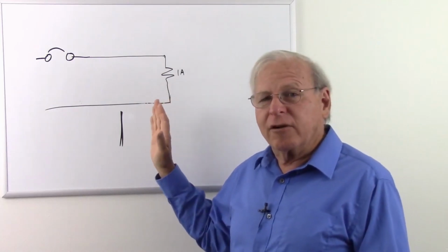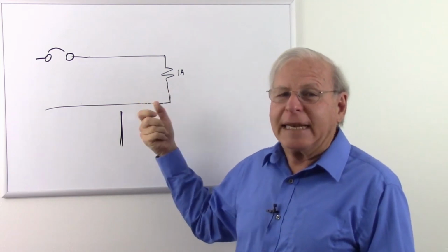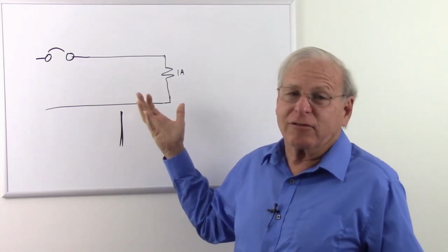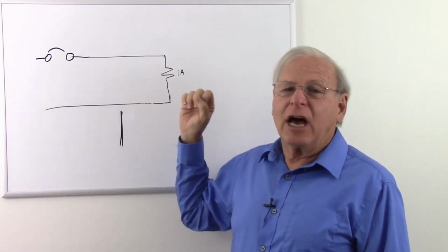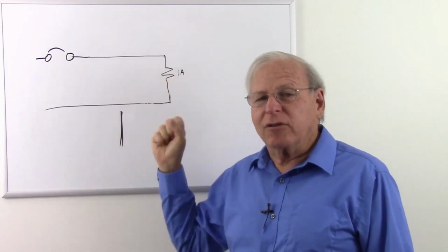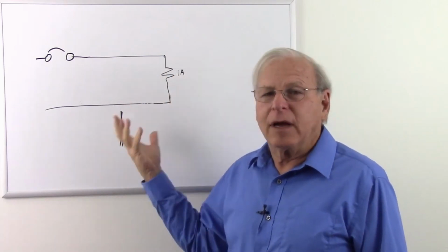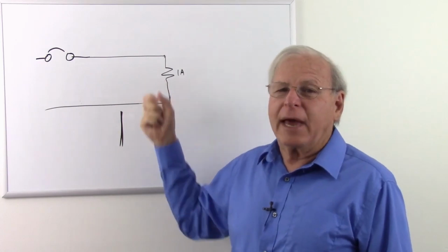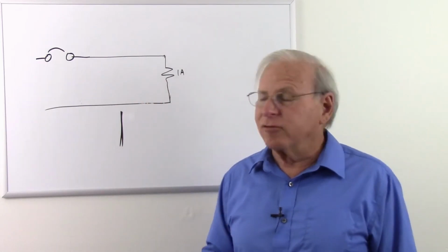But a lot of circuit breakers not only have a bimetallic strip, but they have some kind of a magnetic coil, basically a solenoid or a relay, so that if there is a sudden high current, that will break the circuit immediately. So sometimes a heat controlled circuit breaker, sometimes a magnetically controlled circuit breaker. A lot of them actually use both mechanisms.